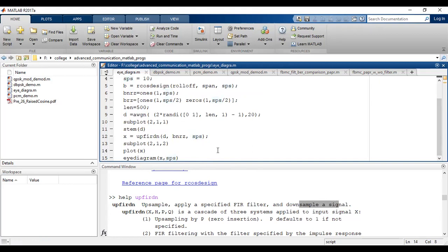So let us run this particular program. What changes do you need to make? Here you have to write, depending on what has been asked, either bnrz (binary non-return-to-zero), binary return-to-zero, polar or bipolar. If it is bipolar, you have to use +1 and -1. Otherwise, if a raised cosine pulse has been asked, find out what beta has been asked, usually 1.5. Those are the standard values.